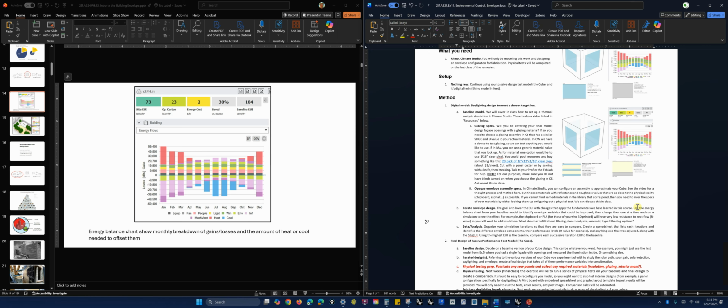So just a couple, particle board. How thick was it? Then another run, add insulation, however you want to do that. Then put in the EUI for each run. I would then pick a baseline, which is the highest EUI, and then just divide each simulation by that baseline, and then you'll get a percentage of change from that original.